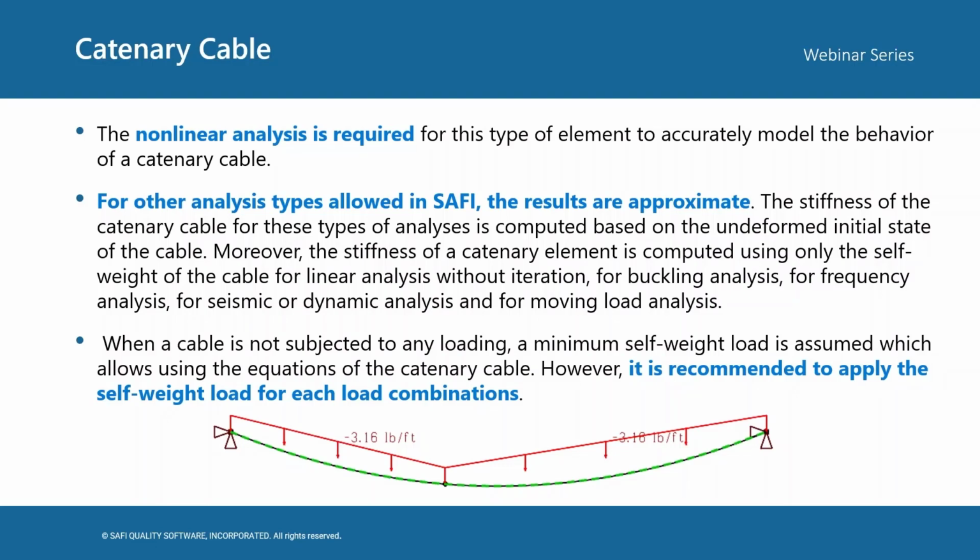When a cable is not subjected to any loading, the minimum self-weight is assumed, which allows using the equations of the catenary cable. However, it is always recommended to apply a self-weight load for each load combination.